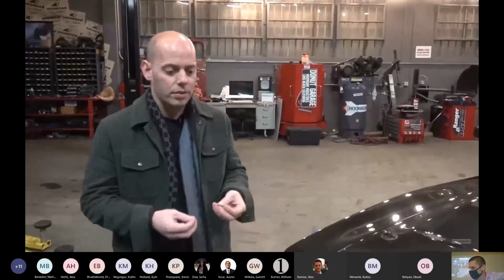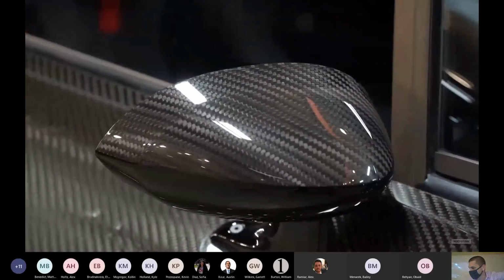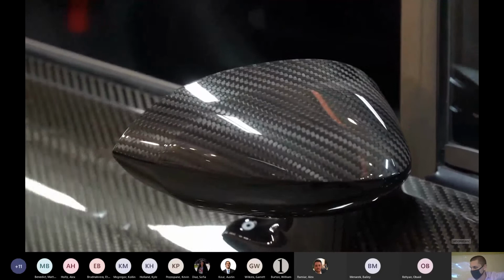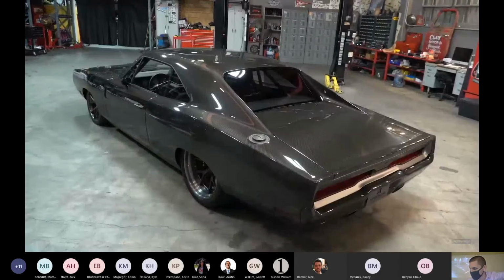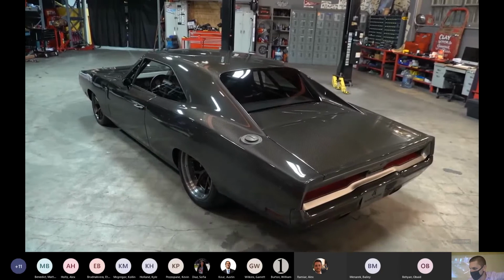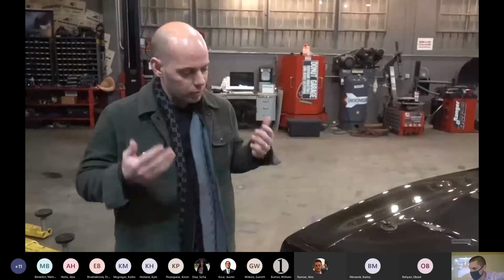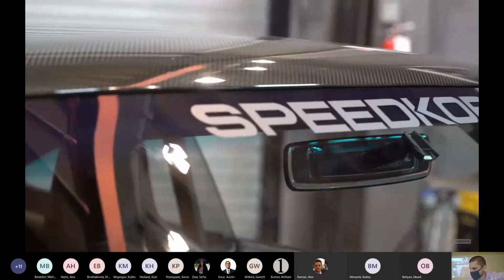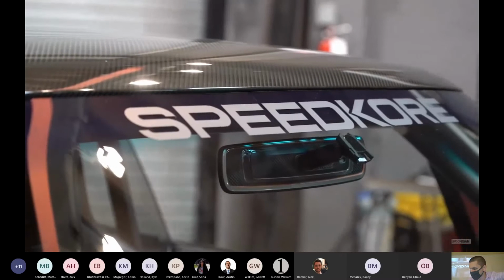Bagged process, the carbon's in there in a mold, and it sucks epoxy from one end to the other, and then it infuses throughout the process. What we use here is the same way they do it on Boeing on the 787s. And this is a pre-preg carbon fiber, and it goes into our molds. We have artisans lay it up and make sure all the lines and the orientation is perfect.